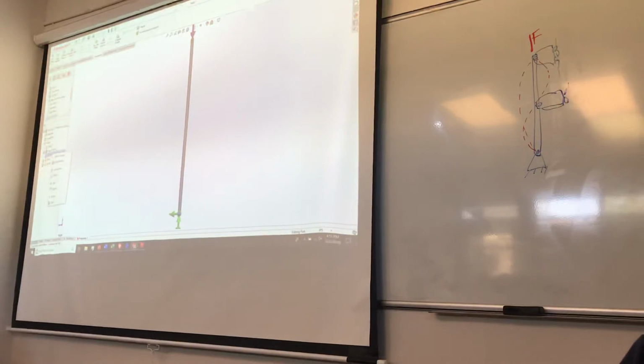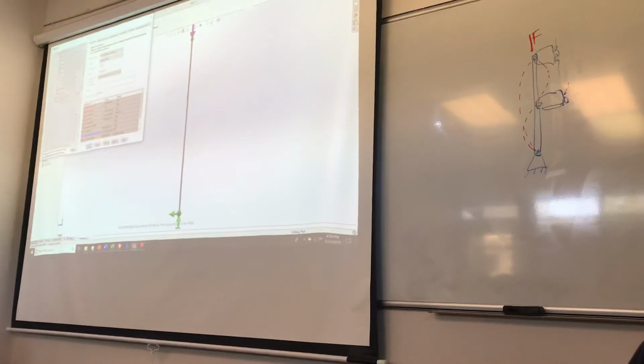It's just because whenever you recalculate them, it doesn't know where it is. Right? And now it's happy. We should be able to create the mesh. And then we run the study. Oh, you're going to say I didn't define a material. Okay. Steel.